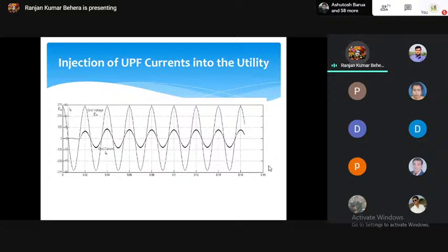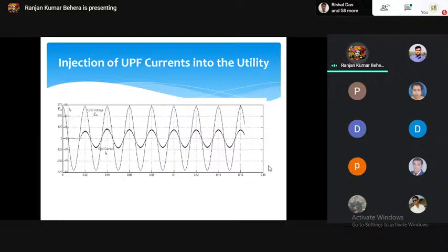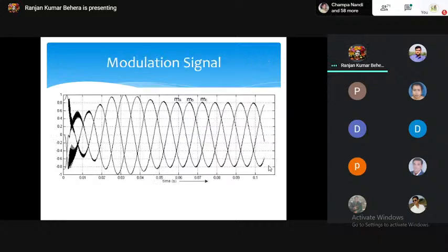But here in this converter, you operate at unity power factor. So reactive power is nearly zero, because VI into cos phi, where cos phi is equal to 1 and sin phi is equal to 0. That is how reactive power is always 0 in a utility friendly converter.